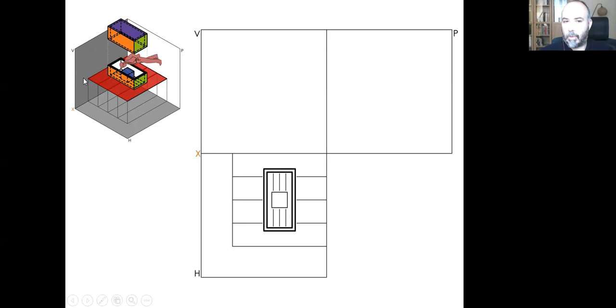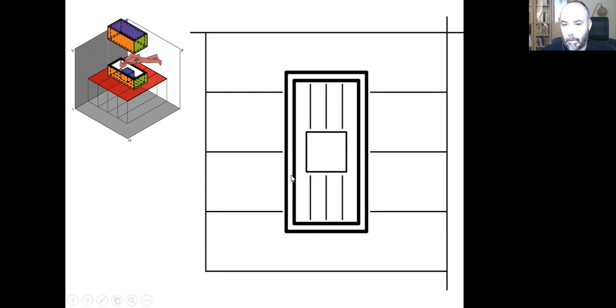And after that, I need to draw the last object that I see. That is this square horizontal plane with profile projecting lines on it. Again, I can use my seventh exercise to copy them because these are the things that I have already seen and now I am seeing as well. So I can just copy this square surface with the profile projecting lines, but again, I need to leave these gaps to indicate that there is level difference between this cut surface and the upper surface of this horizontal plane here.